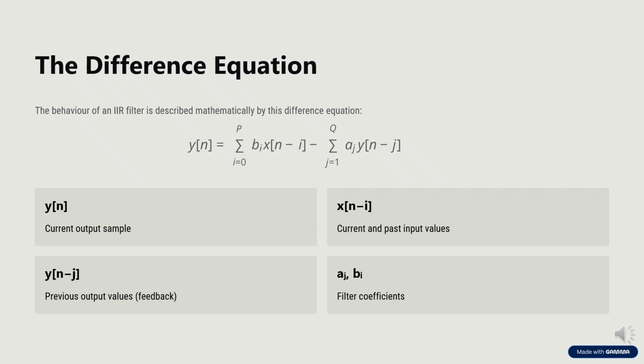Now the second term is much more important, related to the stability of the filter. As I told you, the second part, the a_j that you see, is the pole location of the denominator of the equation that you obtain in the Z plane.